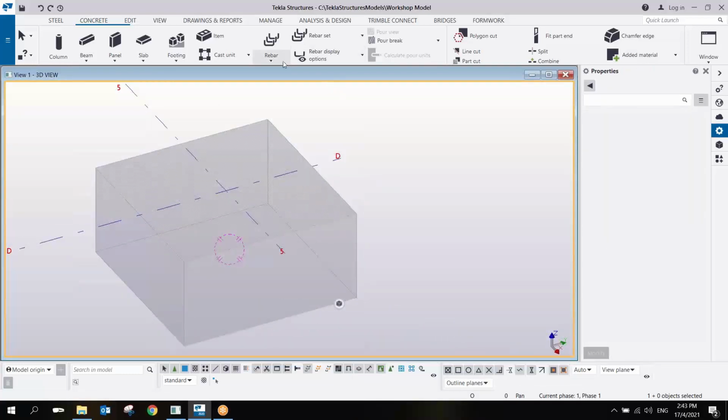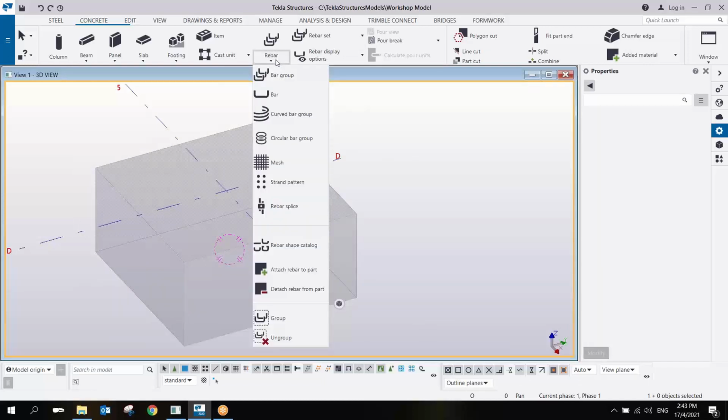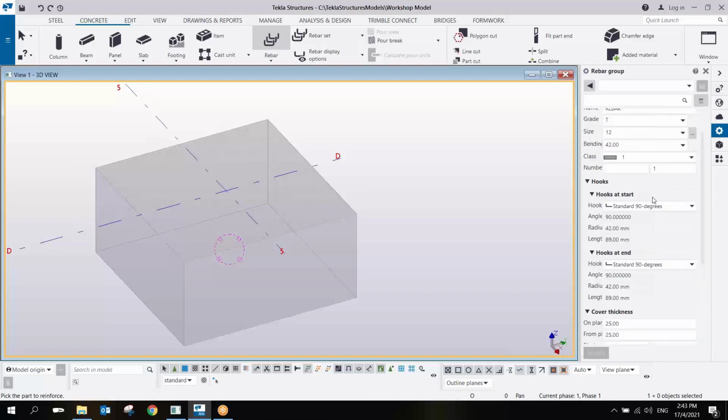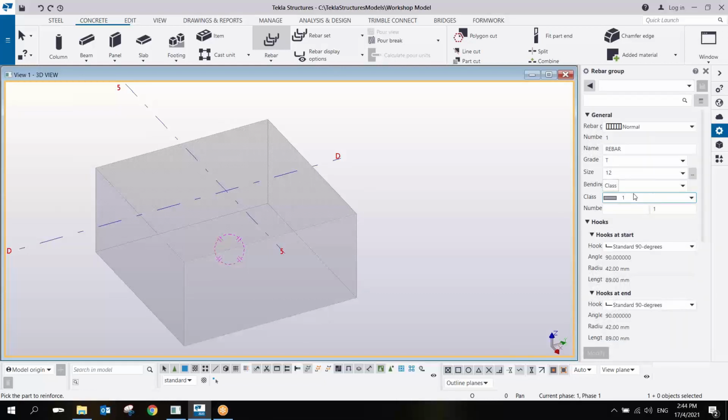There you go. So now I can add the reinforcement here manually. First I will use the reinforcing bar group here. Under the bar group, let me just show you first how we deal with this manually, and then later I will use the system component that we have. So under this, you can see here I have the normal rebar, and let's say I'll type here U bar or main bar. The size here is, let's say, 16. I'll put 3, and then no hook and no hook.